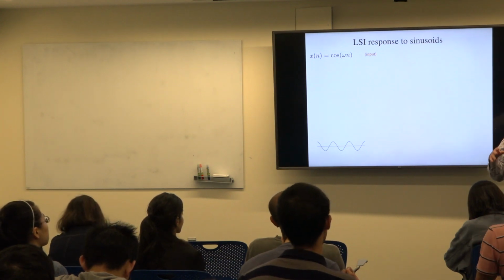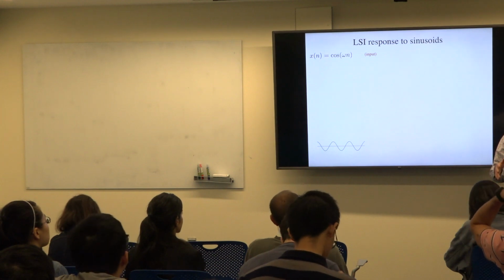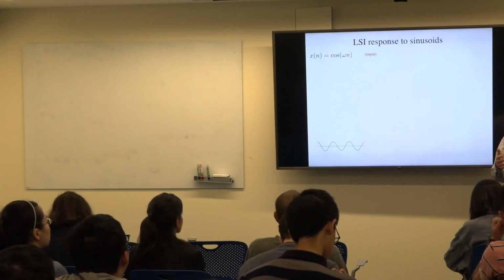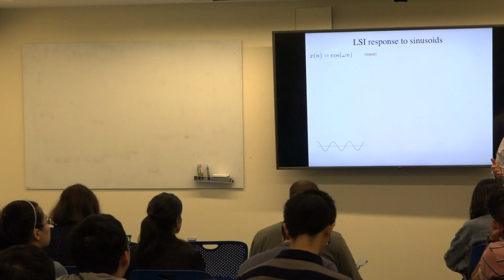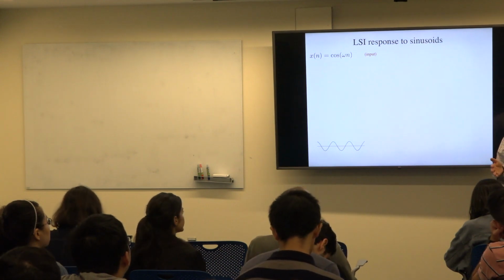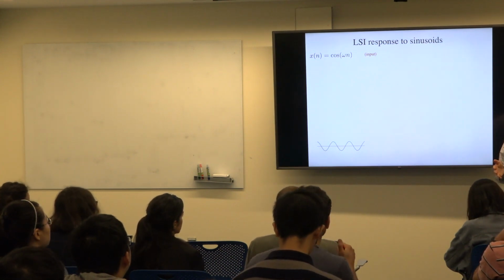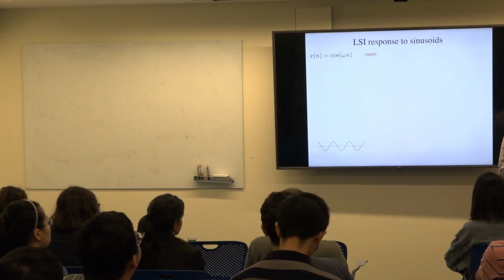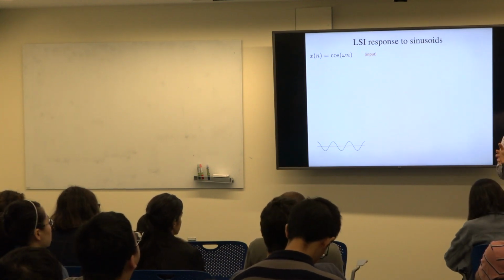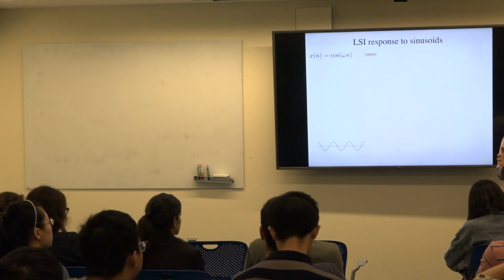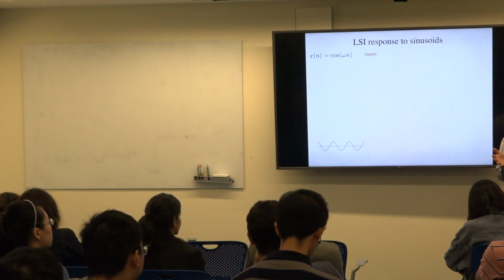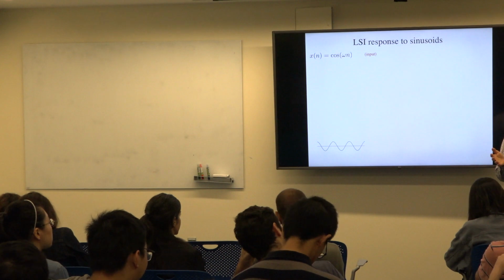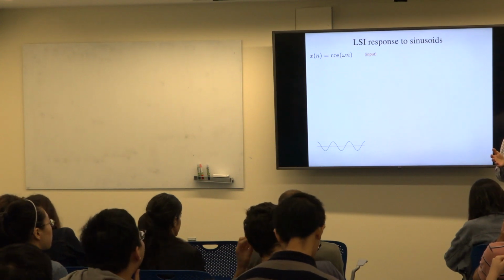The first way, which we started with the first 45 minutes of class, was the same as what we do for any linear system, which is you calculate those impulse responses. Shift-invariant said those impulse responses are all the same as one another shifted, so you only need to measure one of them. And so you measure that vector of responses to a single kick, and you're done summarizing the way the system works, and you can predict its output to anything.